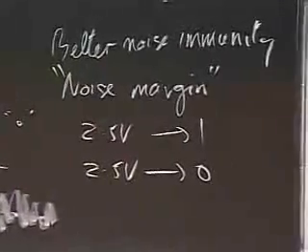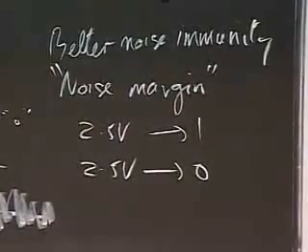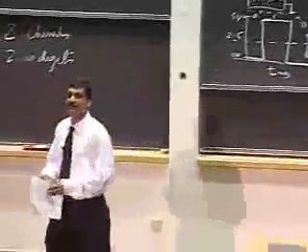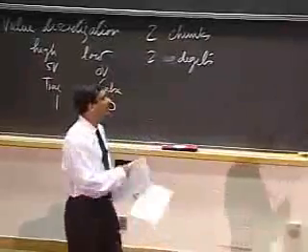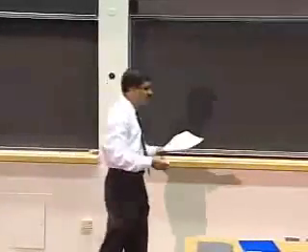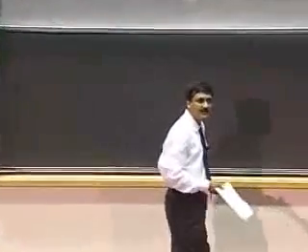So notice that I have a nice little noise margin here, which simply is the English meaning of the term. There is a margin for noise. Even though I can change the signal value by up to 2.5 volts, the receiver will still correctly interpret the signal.